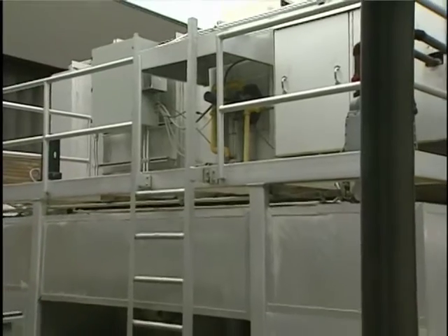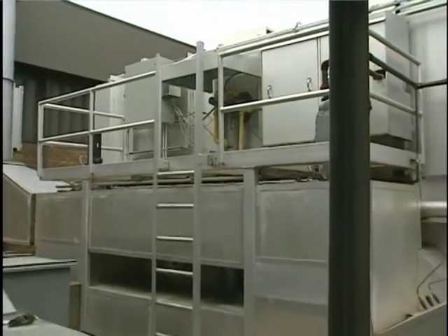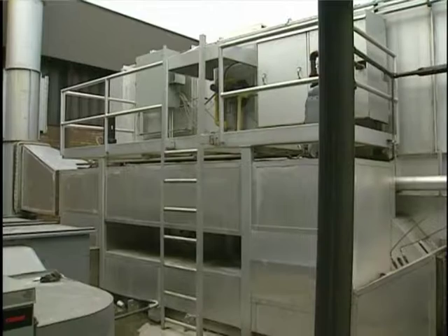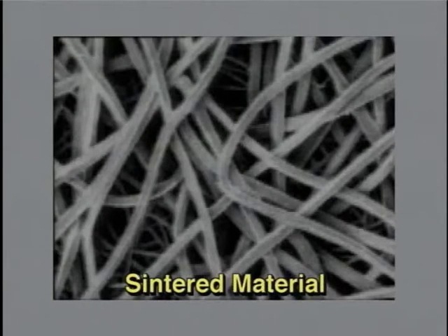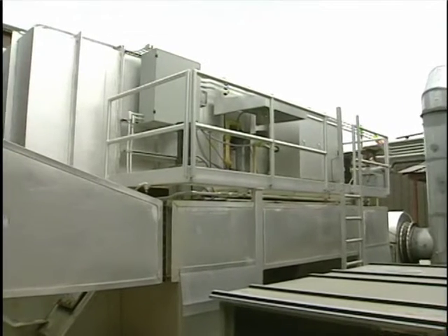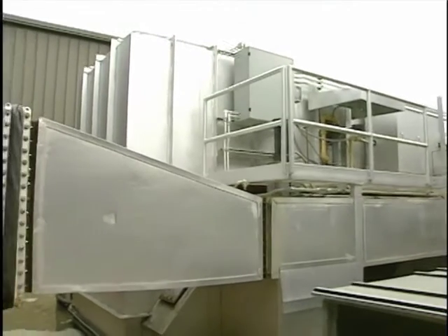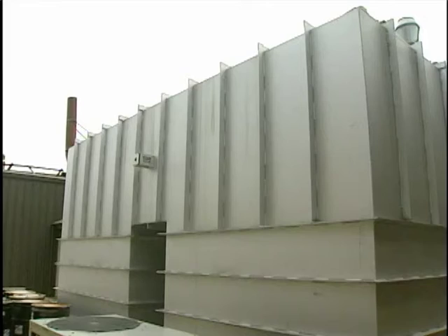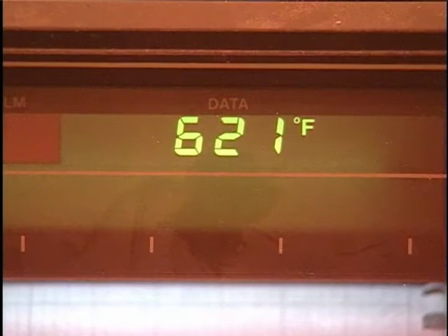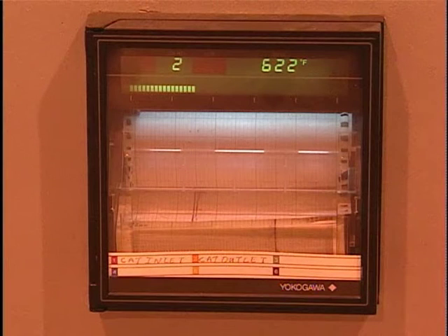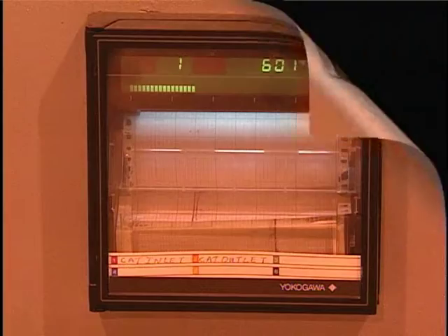This results in a rapid loss of catalyst activity and is caused primarily by the sintering of the catalyst support material. Sintering involves the merging of the support material ridges. As this occurs, the catalyst is trapped below the surface of the support material and is no longer available to the organic compounds. Extremely high temperatures can cause volatilization of the catalyst material.